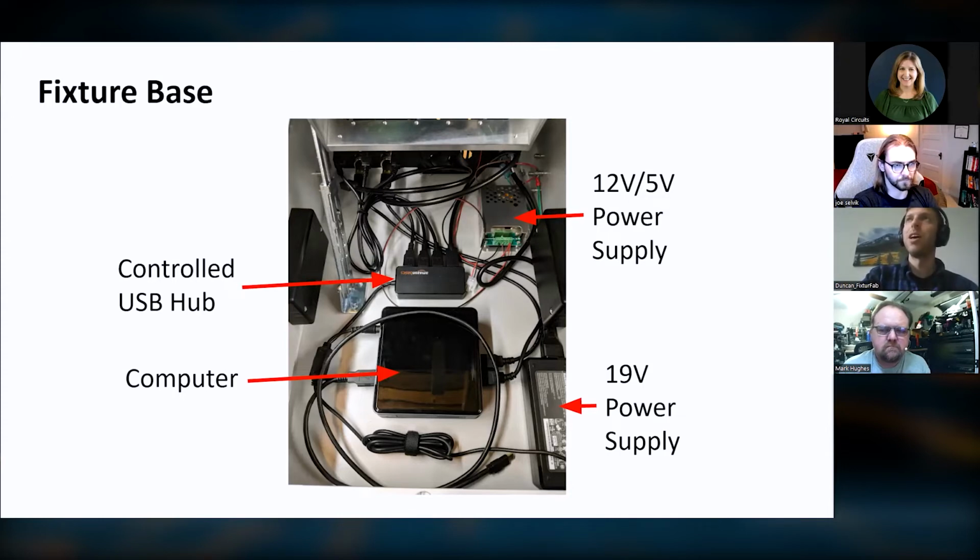your own instrumentation. Another thing that we do quite often is have a test-specific piece of firmware written, whether this is integrated within the actual production code or a special image that we flash on before. That'll give us the ability to send commands directly to the microcontroller and then control various IO. The other way to do this is using boundary scan, which is another technology where you can use a programmer and actually manually check what nets are connected to each other between various ICs that support boundary scan.